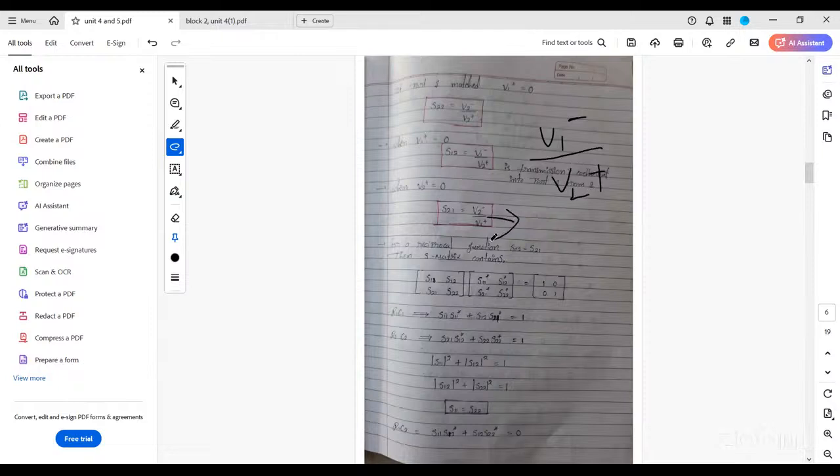Similarly, S21 from the above equation, I am writing as V2 minus by V1 plus. Next, from equation 4.27 in the textbook, or from what we discussed previously, S22 equals V2 minus by V2 plus.